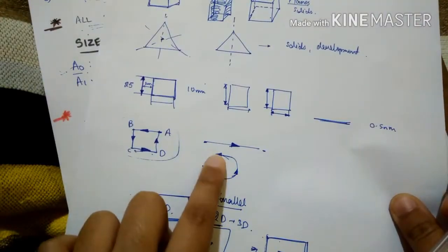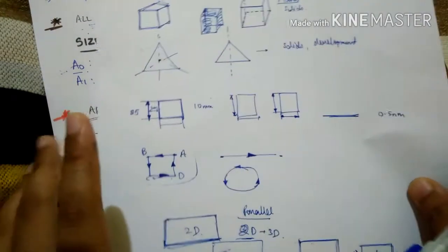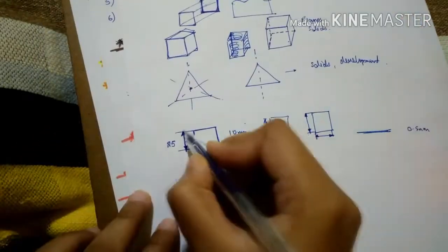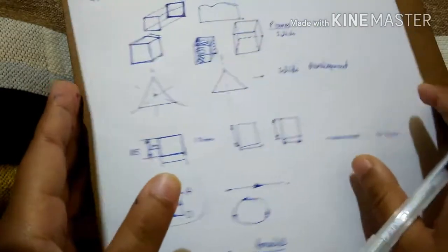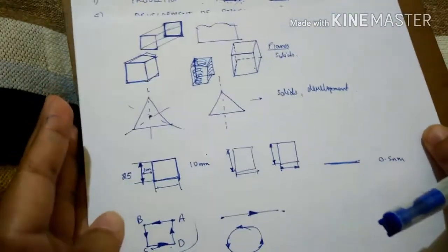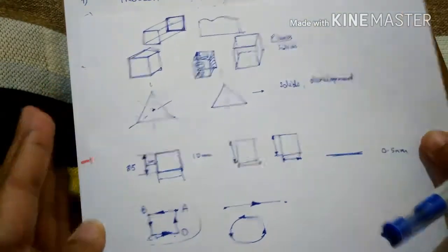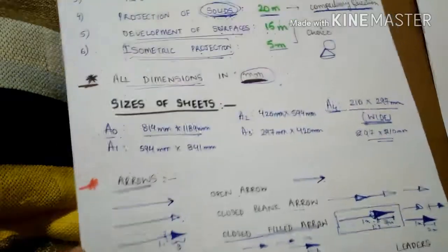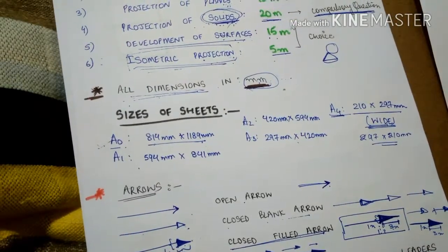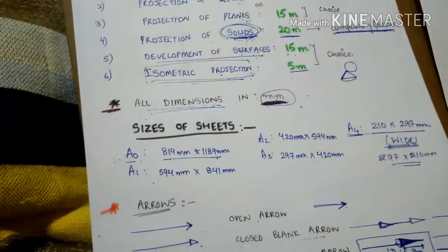As I told you how to form the square and circle, it is very important to mark the leaders. If you draw leaders, perfect arrows, and mark all the dimensions in your sketches, then you get 5 marks for that. So take care of the leaders, imaginary lines, and the thickness of the lines, which should be dark and which should be light. While coming to the planes topic, we'll understand what are thick lines and thin lines.